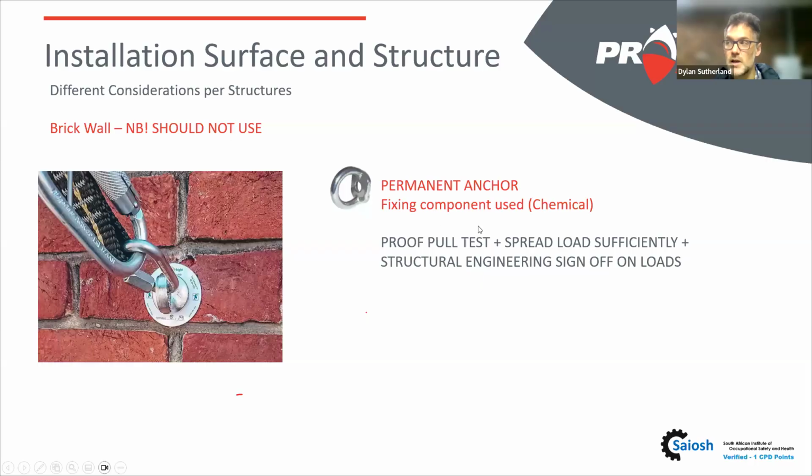Using it with a fixing component being chemical, but along with that, you need to also spread the load. So quite often there's a plate that spreads the load behind the group of bricks. And further to that, there needs to be a structural engineer actually signing it off, and signing it off in the direction that the forces will happen. It doesn't help if we sign this wall off to hold an up and down force. This is going to be a pulling force, and it needs to be able to withstand that. Once again, rather don't do it. Let's find alternatives.